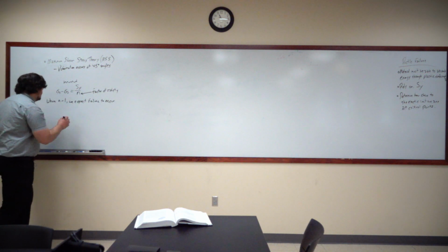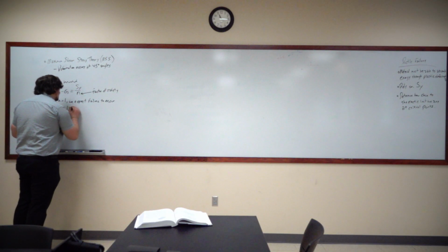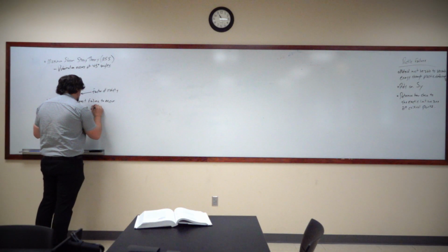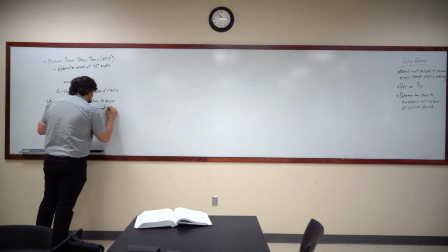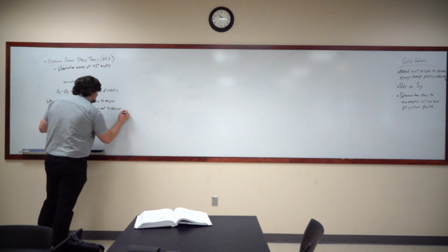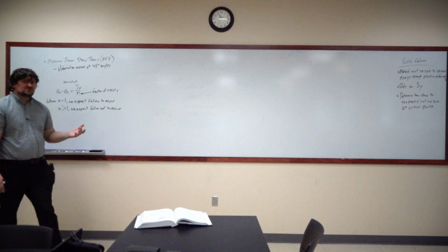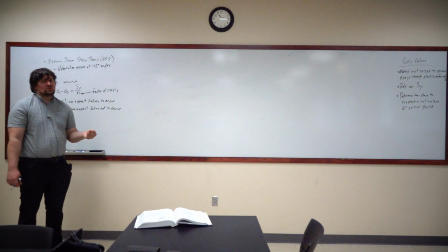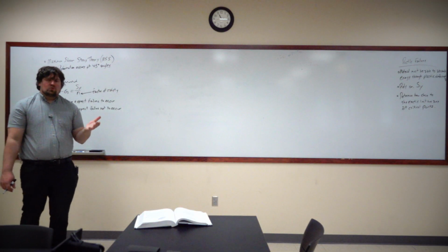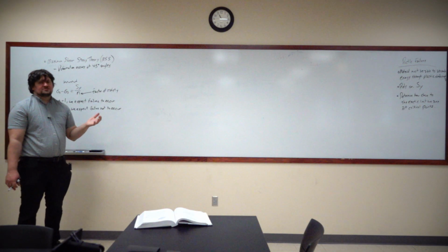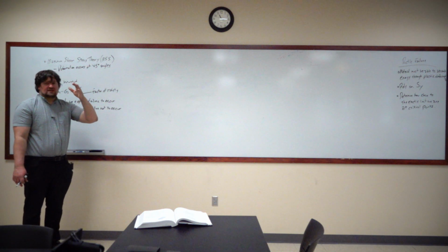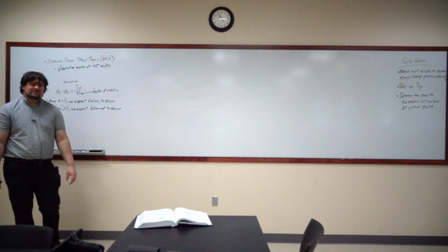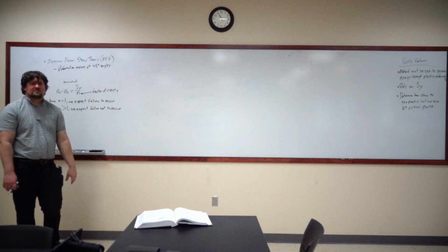It's the tipping point. When n is greater than 1, we expect that failure will not occur. Now in some systems you're going to design with a safety factor that may be 1.15, where we try to be really close to that 1 value without getting all the way to 1. Whereas in some safety factors you're going to be dealing with a factor of safety that may be 10, 15, or 20. And some of that has to do with a little bit of uncertainty. We kind of roll the uncertainty into the factor of safety.